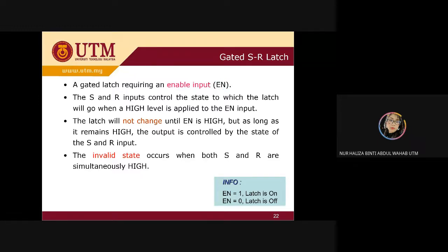The only difference between your gated SR latch and your SR latch is the big differentiation when you have the EN, enable input. So your SR latch will be controlled using your EN input, and when the input is high for your EN input, then it's going to be turned on.